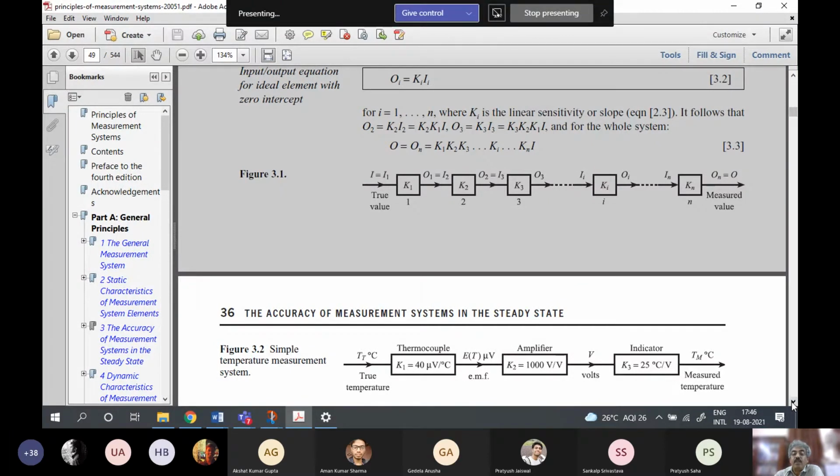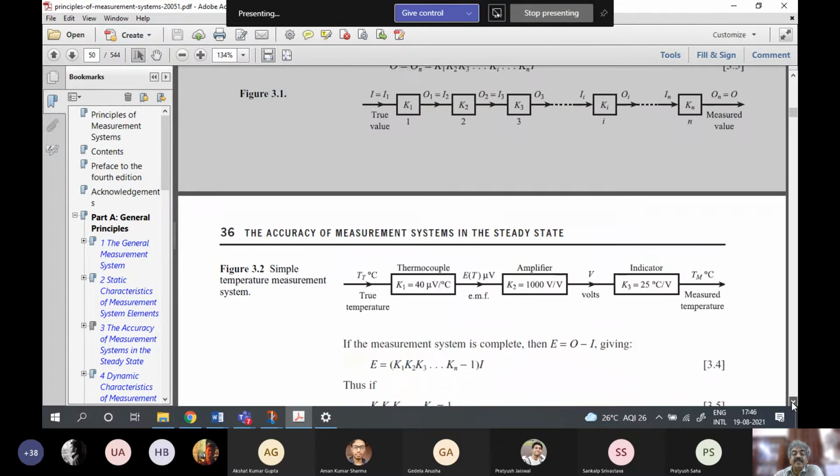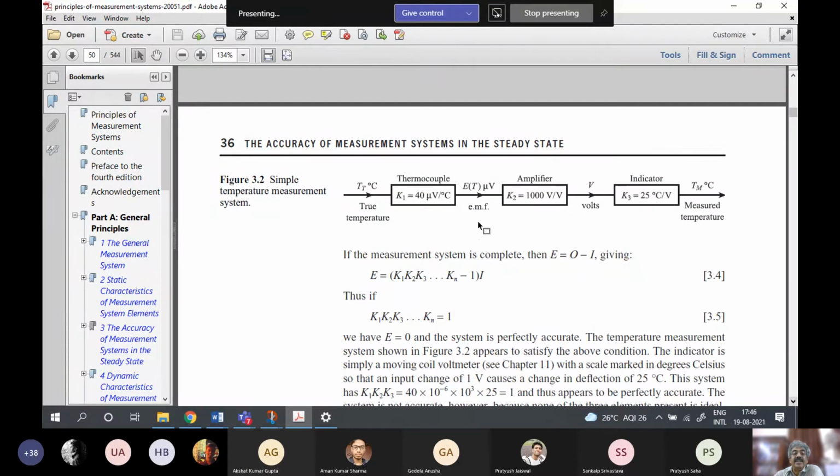So for example, in this case you have a thermocouple. Previously we were talking about a millivolt to current transmitter. That will be required if you want to convert it to current, and that is generally required when you transmit a value over some physical distance, several tens of meters. But if you are making a local measurement, then there's no need to convert to current. We'll later see that a small analog voltage signal can never be transmitted over a long distance, because it is very susceptible to noise.